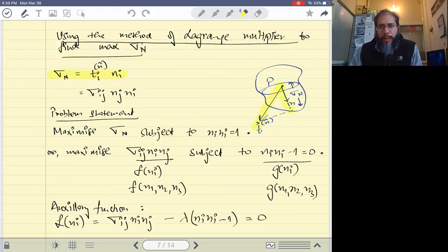Component of a vector in a given direction is nothing but the dot product of the vector with the normal unit vector. So that's what gives us sigma n being t_i n_i. And we know from the Cauchy stress formula that t_i is nothing but sigma_ij n_j. So I can write my stress vector in any normal direction as the dot product of sigma and n, and I can write sigma n as sigma_ij n_i n_j.